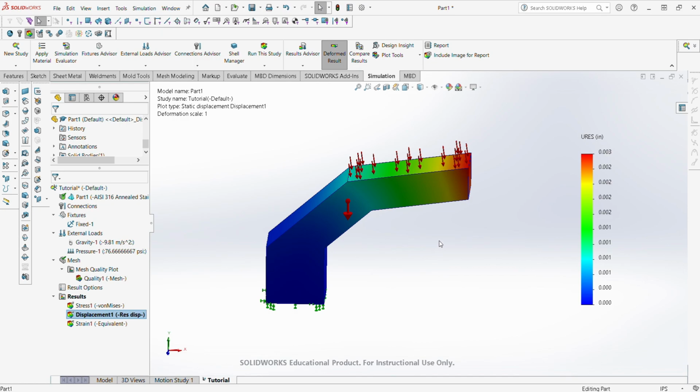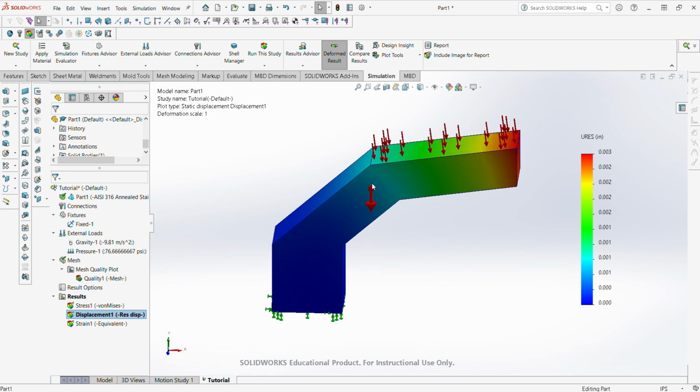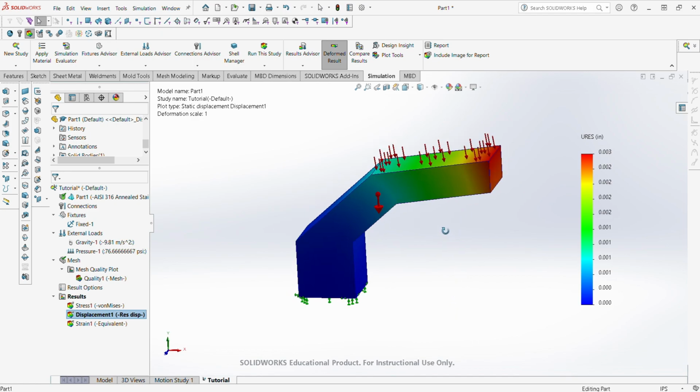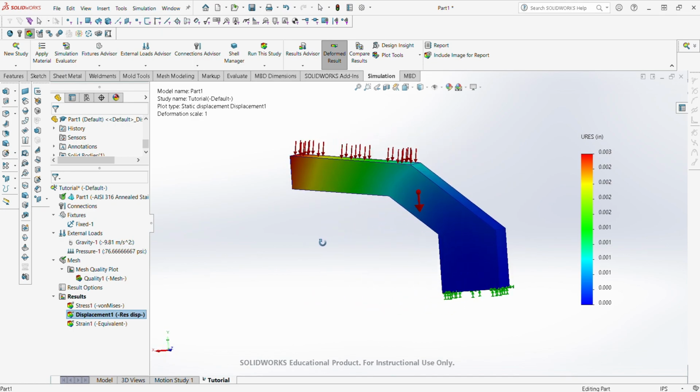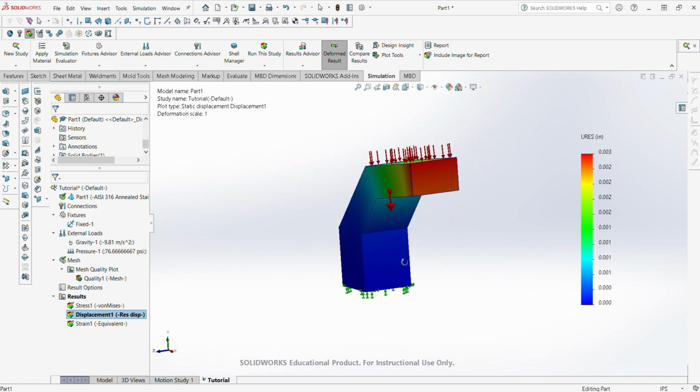If you can set up an FEA that makes sense, and you have the opportunity to field test something, go ahead and field test. Make sure that the FEA data is lining up with what you're seeing in real life, and it's a great way to estimate safety factors and clean up a design before you spend a bunch of money making stuff.